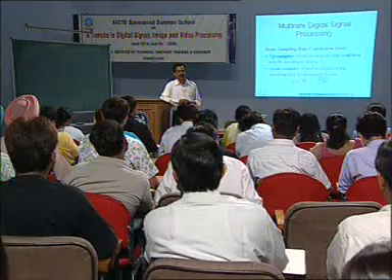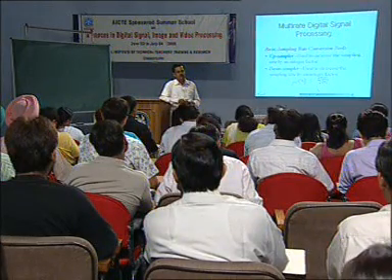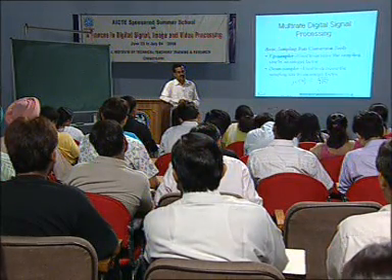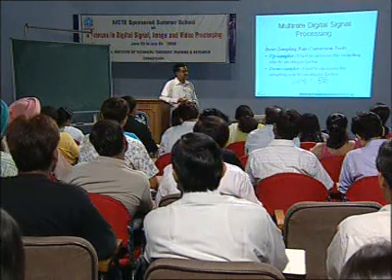Similarly, recently we have suggested another window called the spline window, B spline window function, where we have incorporated two more additional parameters by which you can control the maximally flat frequency response. Maximally flat or MF digital filters can be designed by using B spline window functions. I will explain later on what is a B spline function and how to use the B spline function for the design of digital FIR filter.